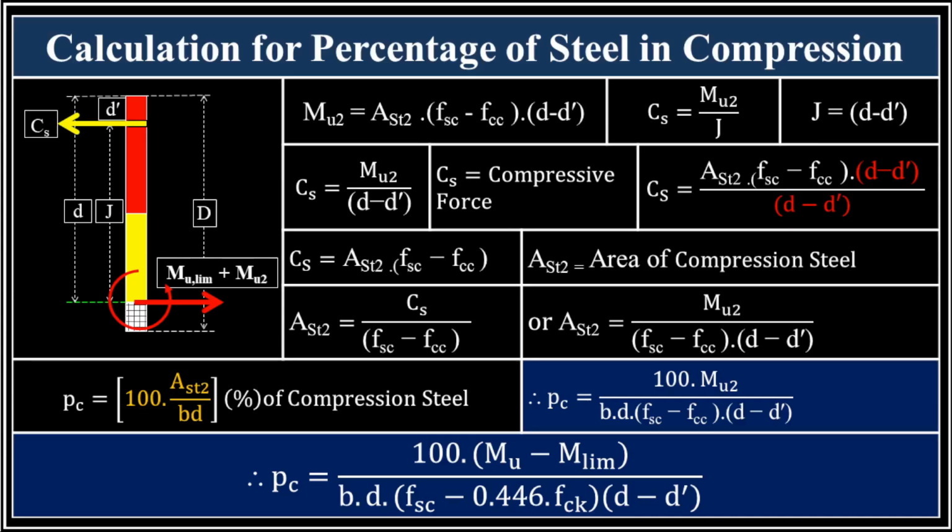While the effective cover in the tension zone is crucial for aspects like durability, fire protection, and proper bonding of the steel, it doesn't directly contribute to the strength gain or diminishing of the concrete section's moment capacity in the same manner that d dot does for the compression steel's contribution.